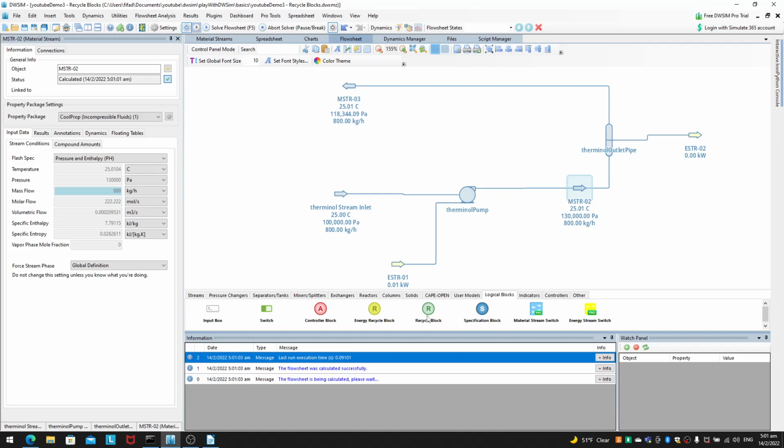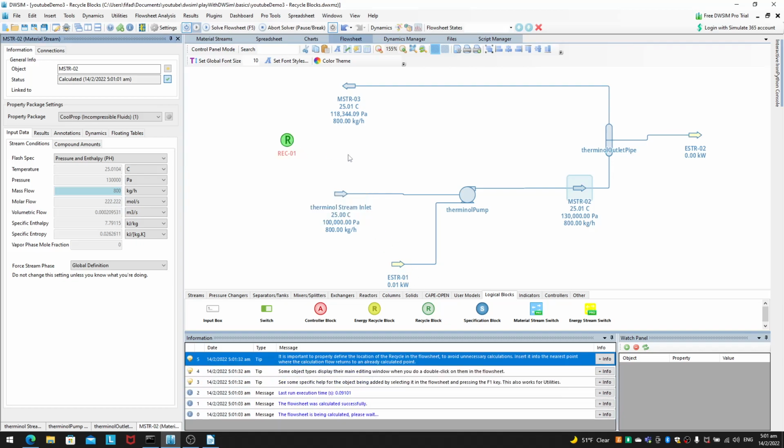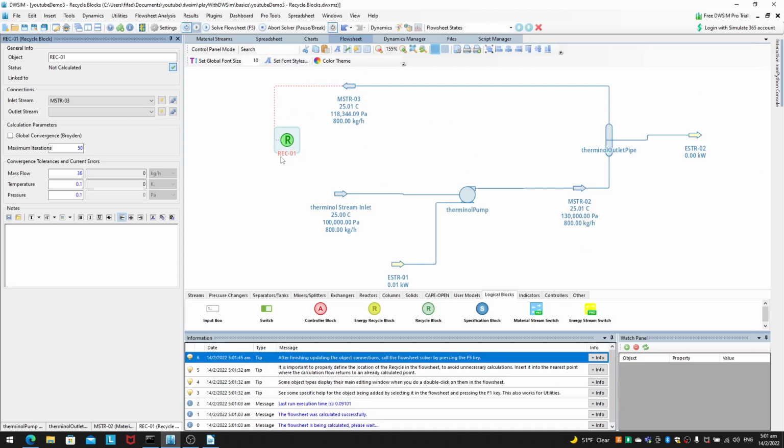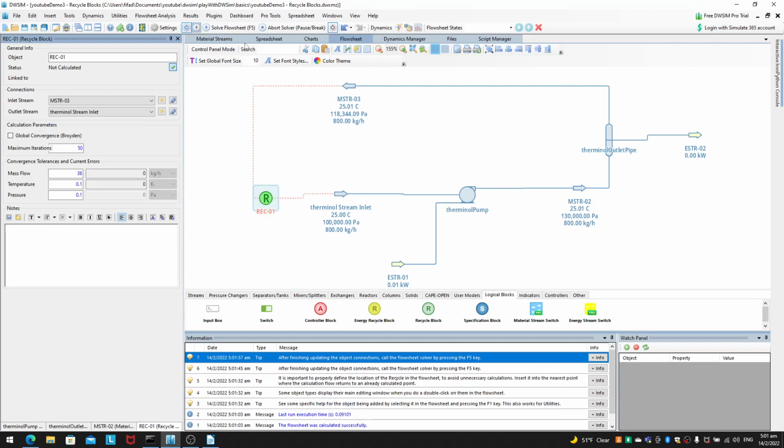Now, in this case, doing the recycle stream will be much easier, because no matter how we iterate, this part will become sort of fixed. And this is actually a good starting strategy to help you iterate such that your loops don't go numerically unstable. So you have to be very familiar with what numerical stability is for solvers in order to understand this recycle stream part.